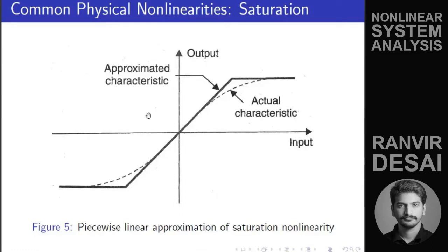As long as, let's say, we stay within these two lines, okay, let's say +5 and -5 volt. Just that we have the limit as 10 volt, but we keep ourselves such that the output is between the range -5 to +5 volt, so that we will get a linear output for the given input. Okay, so this is saturation, first type of nonlinearity.